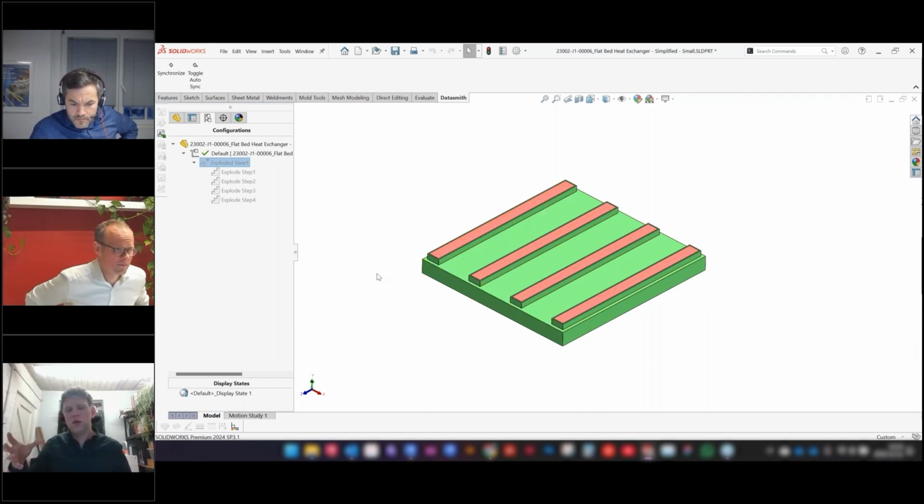So we do a few things. We simplify the geometry and merge the areas of the fans. We also merge the enclosures, and we reduce the complexity of the geometry, but also reduce the complexity of the simulation. When it comes to setting up a simulation, what we are applying to these volumes is momentum sources and heat sources. And the fewer of those we have, the better.